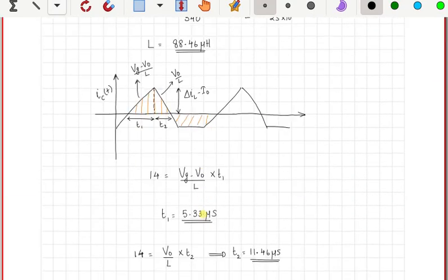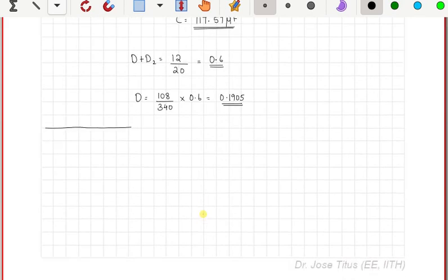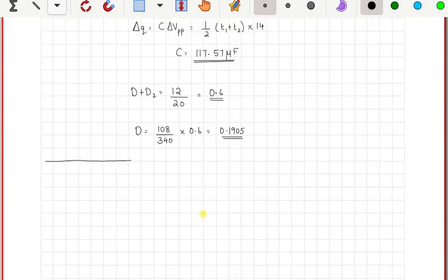So having done all this design, we may now go and build our hardware. You will select the components, L, C and so on, the switch, and then you will build this hardware and operate it. Suppose that you are going to operate it at this constant value of D that you have calculated, similar to what you have done in the simulation. In this case, to your surprise, you will find that the results from the simulation are not exactly like what you get when you build the hardware and operate it with a constant duty ratio.